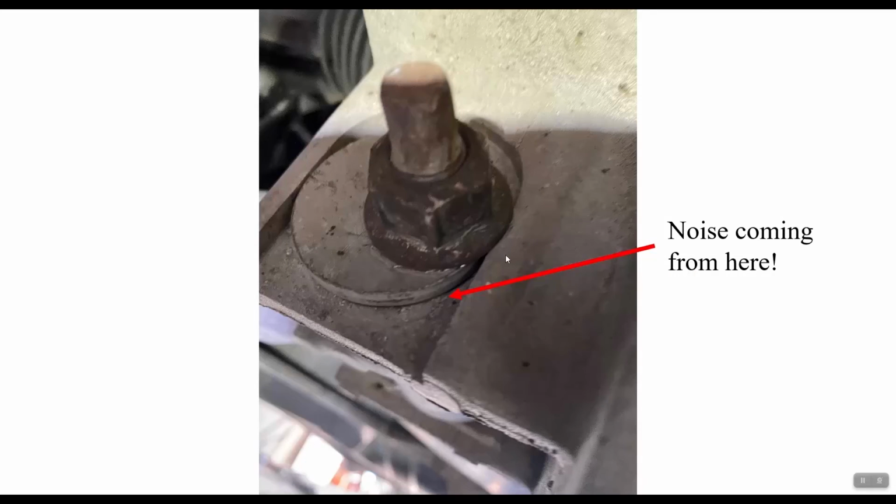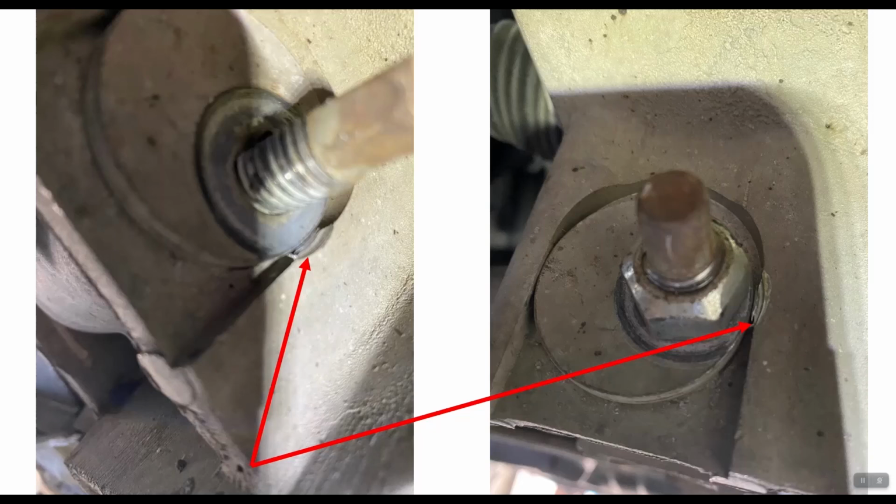The washer then is allowed to vibrate because it is not tight, and using the function generator, we're able to make this washer vibrate, and then once we've got the responding frequency, we can go around and search for where the rattle is coming from. So the fix is to remove the nut, replace it with the correct nut.